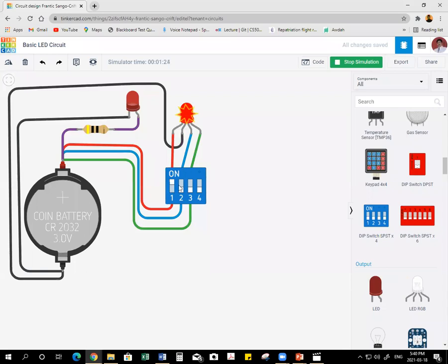Okay, now let us see all the others. If you switch on all, all LEDs are burnt. Okay, so for that we need another resistance in the circuit. As per this single red LED, what we did was in the anode, that is in the positive line, we kept a resistance, not in the negative line, right?